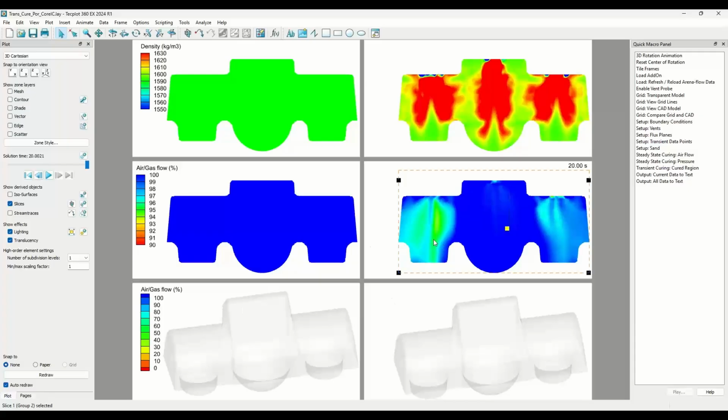It's still around 94-95% cured, so it's very limited. It's just to highlight that because of the venting scheme, we're pulling air through both the dense areas, but also a lot of bypass of air is going through these areas and curing out the center, and then slowly it will make its way and cure the two ends.